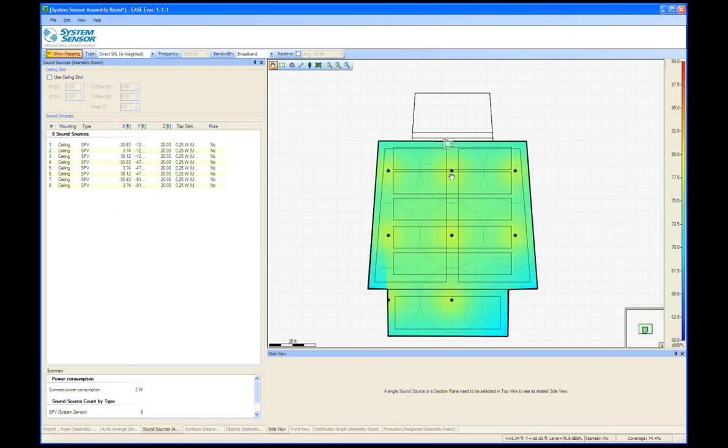I think we do. If we put our cursor close to directly under one of our loudspeaker systems, and I'll move it momentarily, if you look in the status bar down in this area where the cursor is now, you'll see that the SPL is about 77 dB. If I move it to the middle of some of the loudspeakers, it's about 75 dB. So we've only got about a 3 dB deviation from the farthest away of any of our loudspeakers to directly under it. I think that's pretty good in terms of the overall level change.